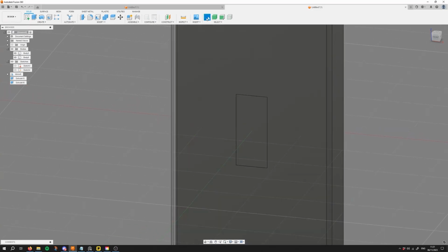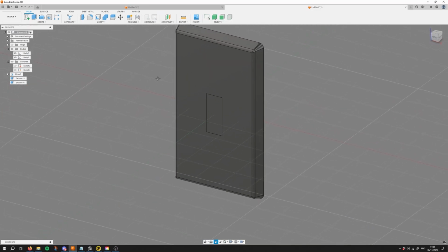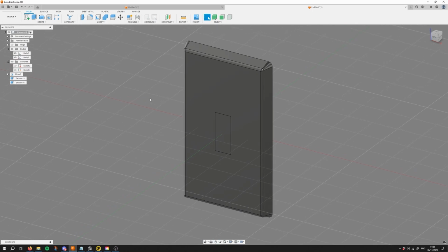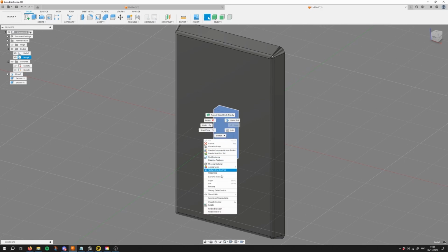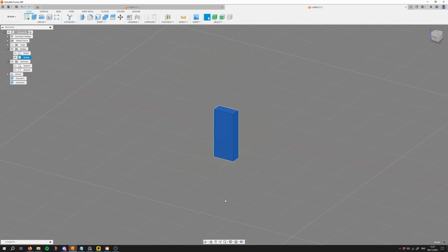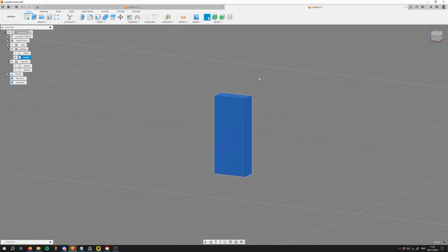Now it's a little hard to see, like this. So if you want to separate your object or isolate it, you go to your object mode, select your object, right click, and go to isolate. This will separate the object and make all other objects invisible, as you can see here in the outliner. This makes it easier to work with separate meshes once you have a really big project.